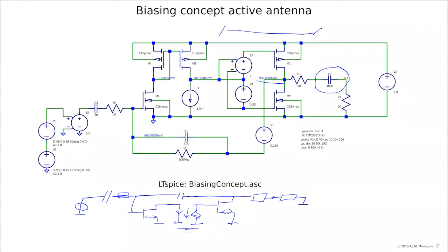We can also say, well, since there is now negative feedback and the whole thing is an amplifier, I can use this amplifier also for the controller to be a controller of negative feedback biasing. And that is basically implemented only by means of a resistor here. You could say this one implements a voltage controlled current source that applies here to the input of the FET and gives the correct setting so that the output voltage will be 900 millivolt.